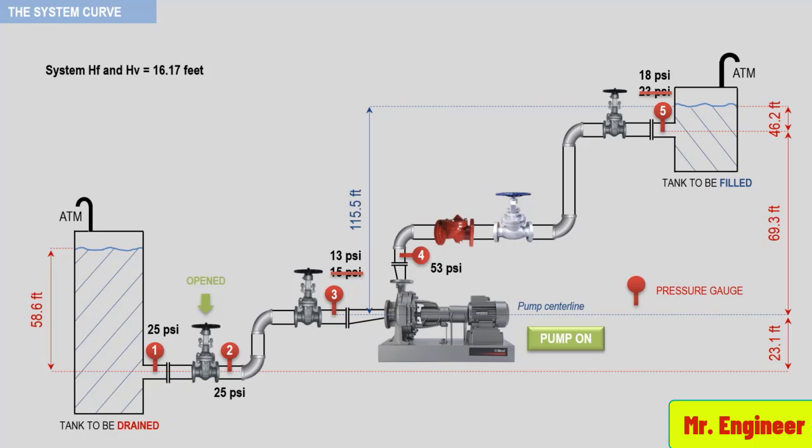Now, regarding pump failure, problematic seals and bearings that need emergency maintenance, in about 80% of all cases, the pump was telling the operators what the problem is, hours, days, and weeks before the failure even occurs. What is really happening is that no one is interpreting the information on the gauges. This detailed discussion on the friction head and velocity head probably has you ready to throw this course into the garbage. But really, this method is a powerful tool to know the characteristics of your system.